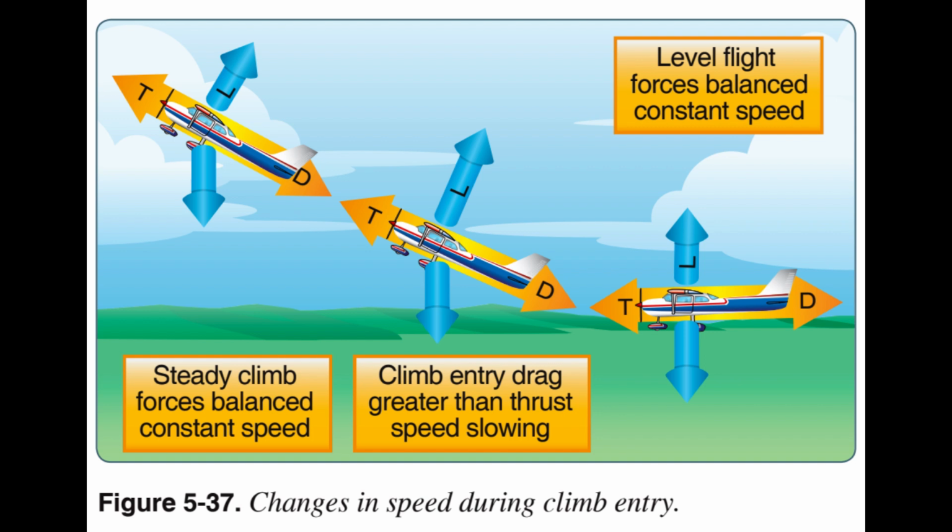Therefore, the angle of climb for climb performance is dependent on the amount of excess thrust available to overcome a portion of weight. Note that aircraft are able to sustain a climb due to excess thrust. When the excess thrust is gone, the aircraft is no longer able to climb. At this point, the aircraft has reached its absolute ceiling. Forces in descents.